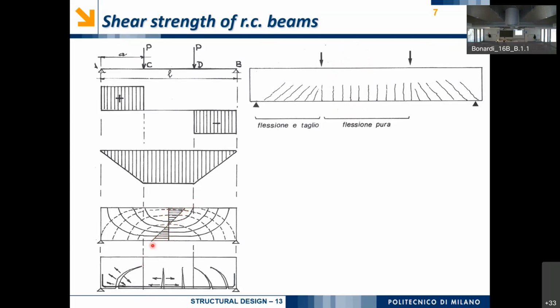vertical before will deform, and it will rotate. This deformation comprises both compression strains at the top of the structure and tensile strains at the bottom. We can plot continuous solid lines here that indicate something that is very simple to understand: the same level of compression of different fibers in different parts of the structure. So, if we compute the strain plot here, this strain level will be constant from here to all the points that are indicated by this line.